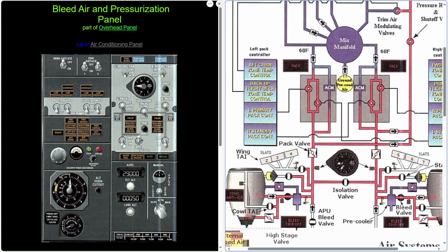So we can see that the bleed air right here, that's this switch in here, that's getting the air. This APU bleed valve, that's right here. Then we go up through the air cycle machine, but first we have the indication of pressure, and that is right here. This is telling you how much pressure you need to start or operate the pneumatic system or the bleed air system. And it's usually around 30 psi is what you want to see on your pressure.